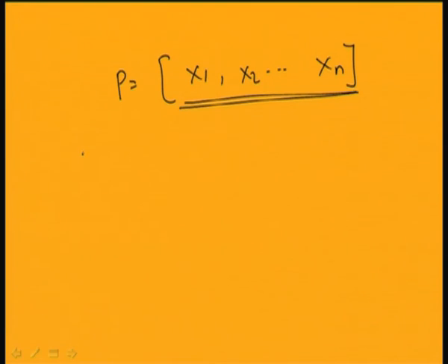The free vibration u can be written as C1 x1 plus C2 x2 plus Cn xn, where C represents the modal participation of different modes in the resulting free vibration. By using the orthogonality principle of normal modes, we can find this C.